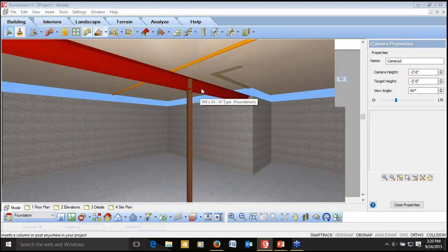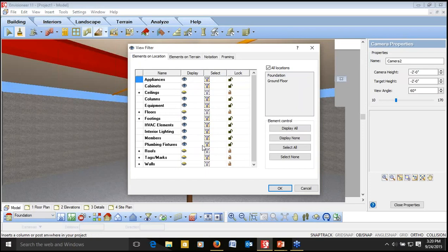So when you're trying to coordinate any mechanical or electrical elements that are being put in, draw those particular elements, especially those that you think may interfere with some structural elements that are part of your design. And then when I'm printing this out, I can turn off the visibility of different elements that are only important to that particular trade. So I could turn off absolutely everything except my walls. Maybe I keep on my structural members and my electrical elements.